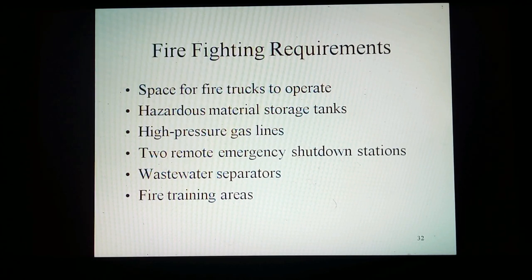However, extensive use of shutdown valves may not be needed, since the increased complexity of the system will require a greater degree of preventive maintenance if unwarranted shutdowns are to be avoided. Shut-off valves, sometimes known as station isolation valves, shall be provided on all gas and product pipelines into and out of the plant. The bypass line with a normally shut valve may be required between plant inlet and discharge lines. All station isolation valves and bypass valves, if any, should be located at a minimum distance of 75 meters but not more than 150 meters from any part of the planned operations.